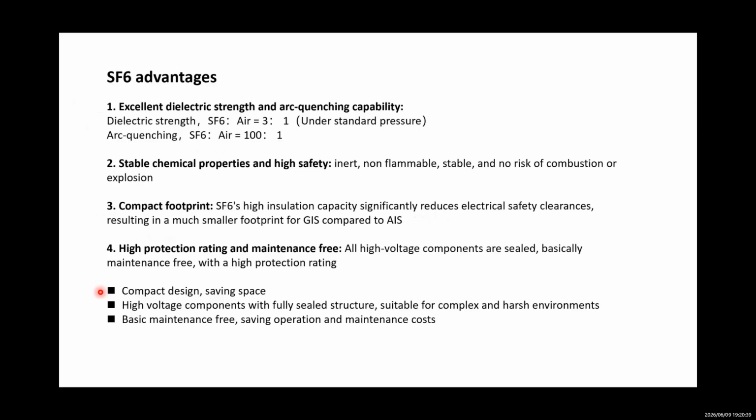So these are the GIS advantages: compact design, saving space or footprint on site, high voltage components in a fully sealed structure suitable for complex or very harsh environments, and basically maintenance free, saving operation and maintenance cost. These are the advantages of SF6 and SF6 GIS cabinets.